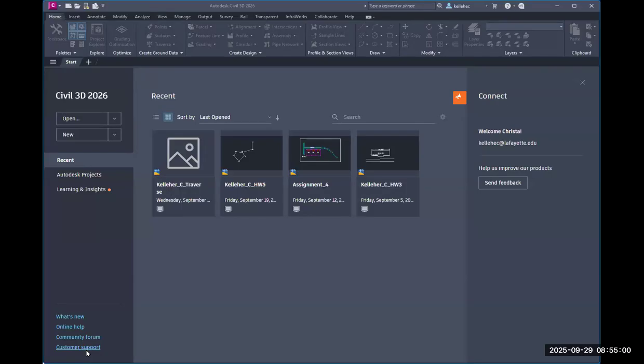All right, folks. Today I'm going to take you through drawing your traverse in lab and extracting coordinates and geometrics from your points. Before you get started, you want to make sure that you have a nice table made showing your elevations for each point by foresight and also your horizontal distances from your foresights.